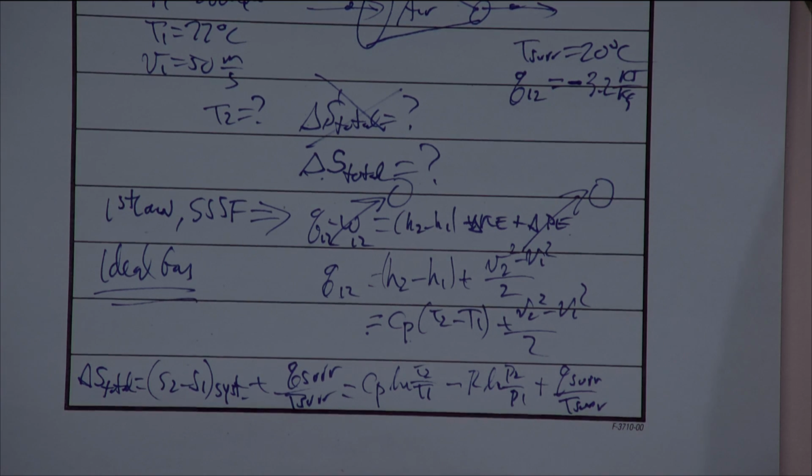So we would expect that as we accelerate, the internal energy, or really I should say enthalpy, not internal energy, but we would suspect that the enthalpy is going to have to drop as the kinetic energy rises, and as such, we would expect that T2 is going to be less than T1. After all, enthalpy and internal energy are functions of temperature, right? As the temperature goes up, the enthalpy and internal energy go up. As the temperature drops, the enthalpy and internal energy go down.